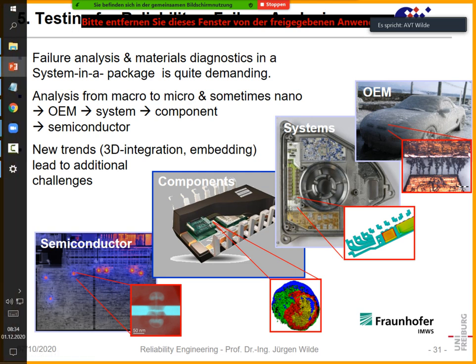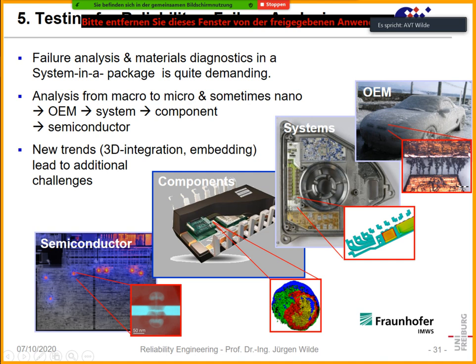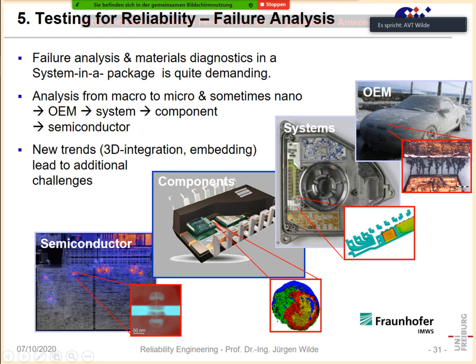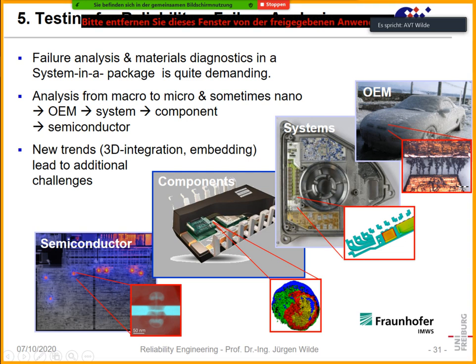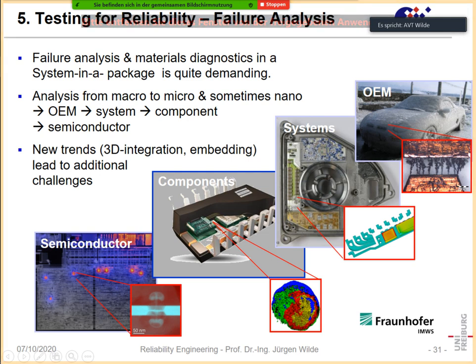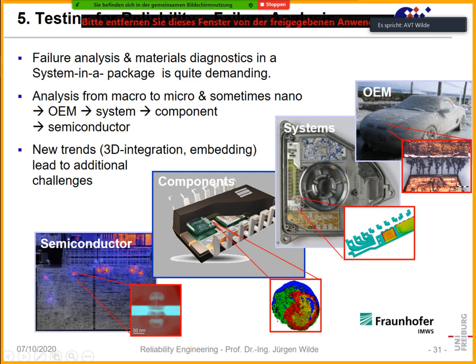circuit. So there are quite a number of strategies how to find the defects. In most cases, or in many cases, in systems from the field, the device is dead, so we can have no longer electrical measurements. In some cases where the device just shows faults, so that means it is defective somehow, but it is still working, we can have different methods. For instance, we can use thermography, and sometimes we can find some hotspots. A hotspot is a location where we typically have an increased power dissipation, and that power dissipation leads to heating, and that heating can be seen sometimes, but that's a rare condition.